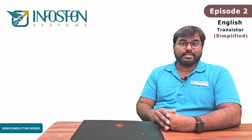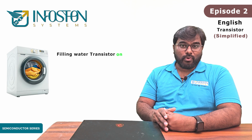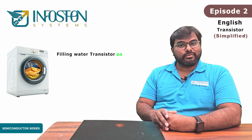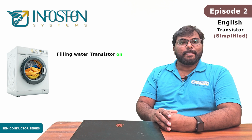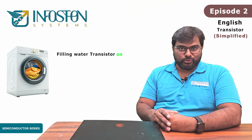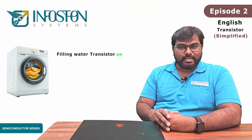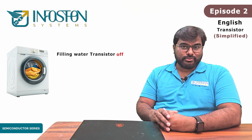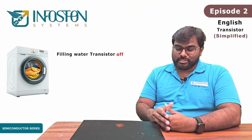So how it happens, the processor will send the signal to that filling water transistor gate. So if that transistor receives signal 1, then it will switch on the transistor. Then the mechanism will start and the valve will be opened and the water will flow to the drum. So once that water reaches the limit, the processor will send the 0 signal to the gate, then the transistor will be switched off, then the valve will be closed.